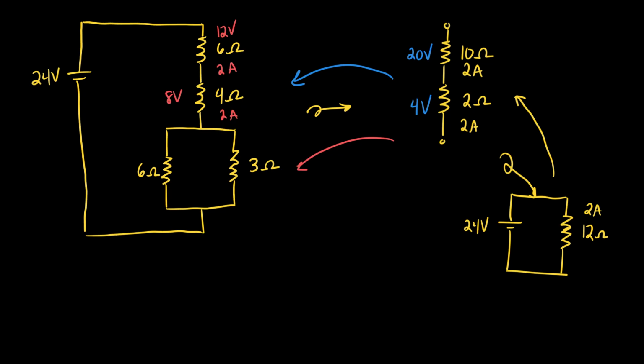All right, I'm going to take that other one. I'm going back to a parallel element. Parallel elements do not have the same current, they have the same voltage. So I have 4 volts of voltage here. I will apply 4 volts here and 4 volts here.